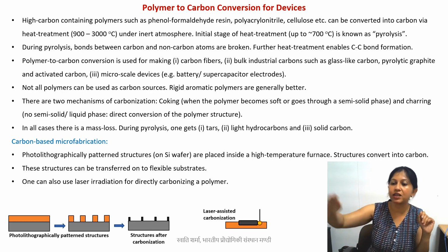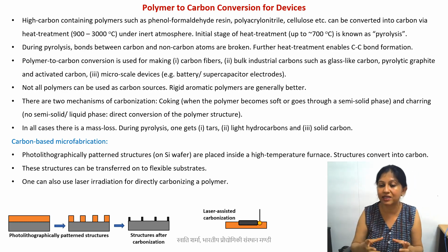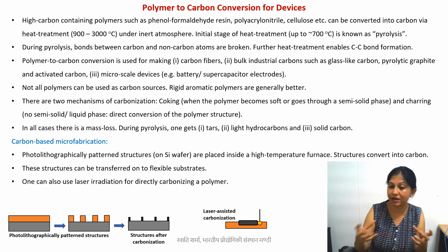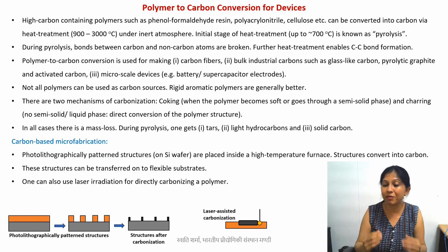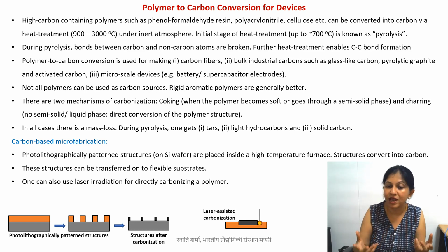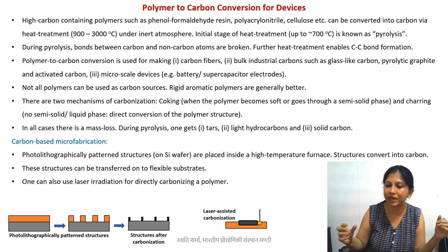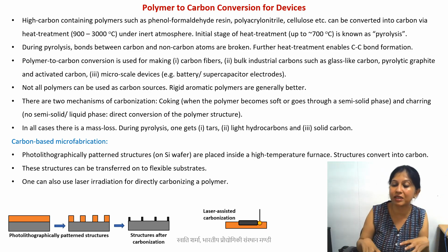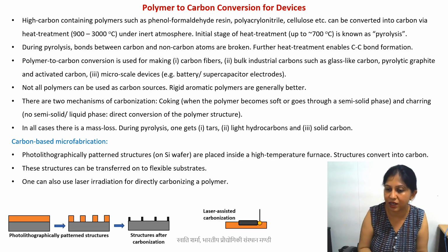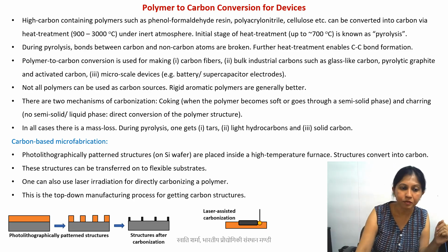as opposed to the furnace treatment, where we are heating the material very slowly, 2 degrees centigrade per minute. So all the gases that are being formed, all the non-carbon atoms that are being released, we give them enough time to release. But in the case of lasers, the process is so fast that they just abruptly release, and that is how they create a lot of pores in the material. And also the purity of such carbons is not more than 80%. So depending on the applications, whether or not you want to make laser-assisted carbon, you can decide.